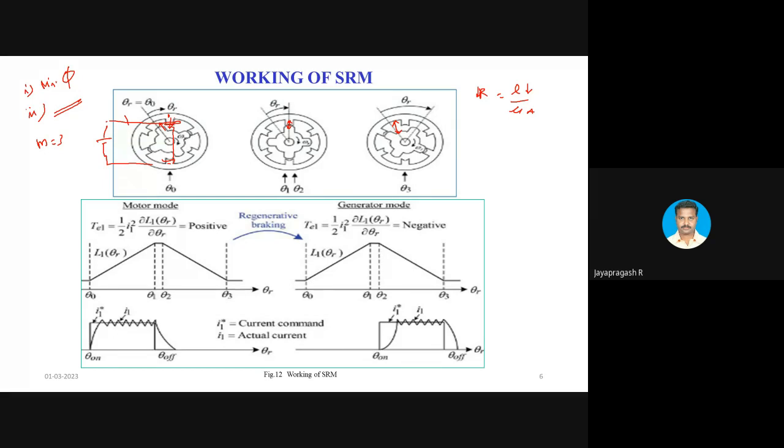We know the tendency of magnetic flux lines. In an electrical machine, each and every magnetic flux line will act as a separate magnetic circuit, and the magnetic circuit is a closed one. If we consider a permanent magnet, the flux lines originate from the north pole and sink at the south pole outside the magnet. Inside the magnet, it is from south to north. So each magnetic flux line can be treated as an individual magnetic circuit. Certainly, it will be completing its path.